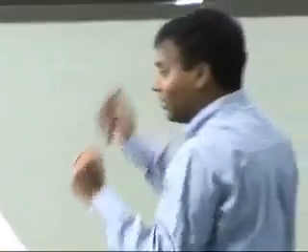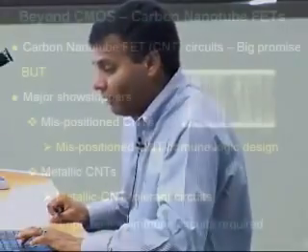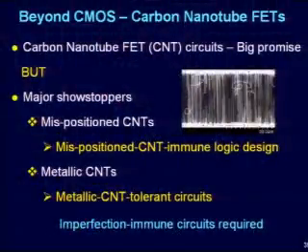We know the assembly code or the binary of what you were running on the post-silicon validation platform, and we have the information from the recorders, and we look for self-consistency: whatever you read was the same thing that you wrote, and so on, to be able to localize these bugs. Again, this is a 2,000 feet view, but it does work in real life.